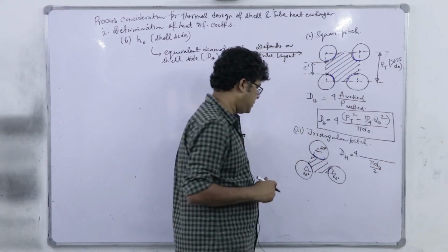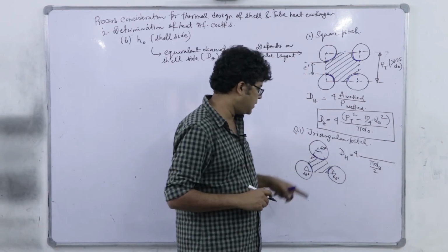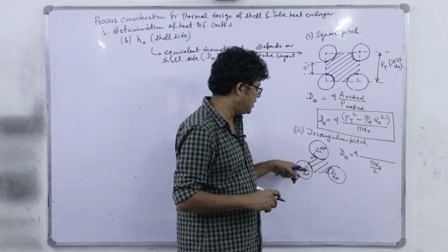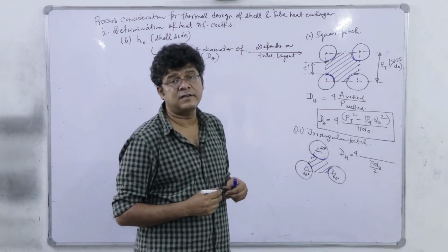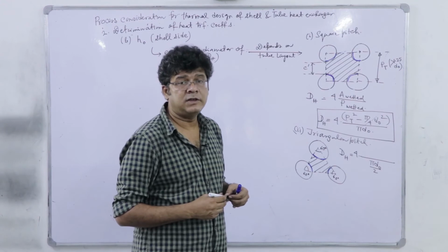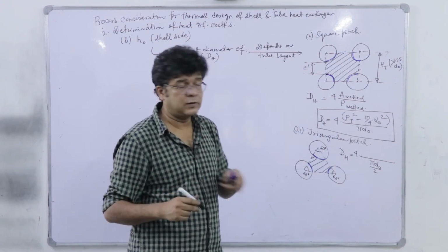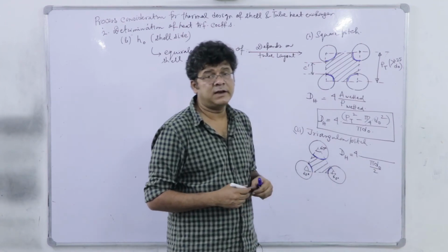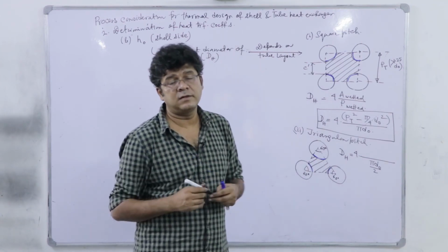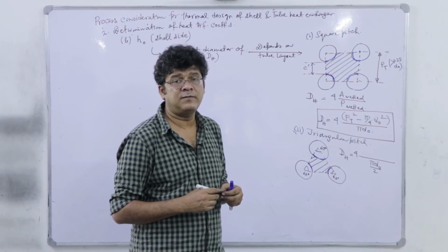Now, here it is the wetted area. It is the area of this equilateral triangle, and we have to subtract again half of the cross sectional area of an individual tube, right, considering its outer perimeter. But why half? Again 60, 60, 60, 180. So, 360 corresponds to pi d naught square by 4 area.